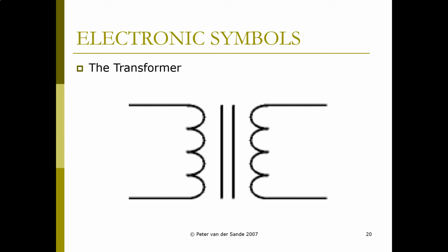Or simply having the same number of coils on both sides, as can be seen in this diagram, is used to simply isolate two circuits, because the AC signal will pass through the magnetic material from the left coil to the right coil, but there's no electrical connection between the two, therefore acting like an isolation transformer in this case.